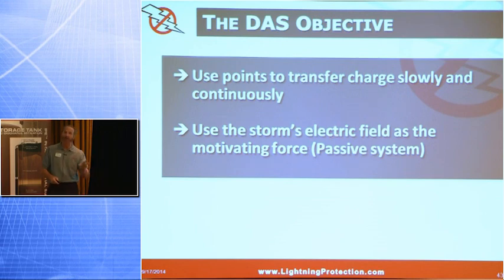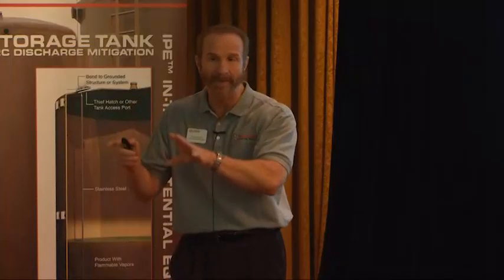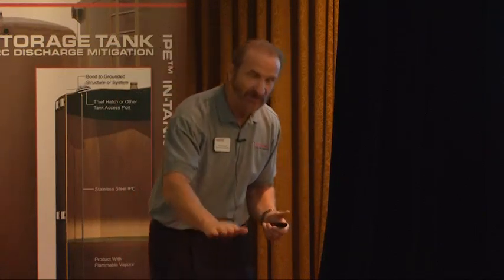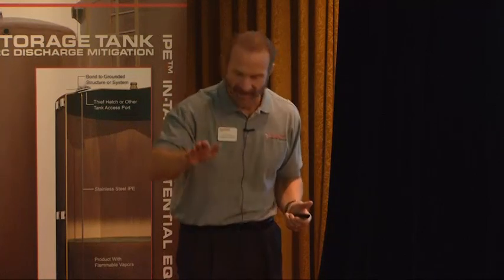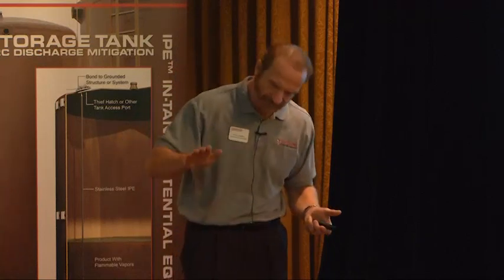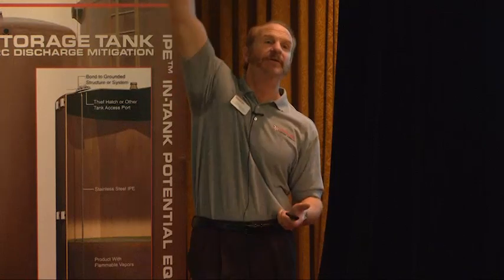And we do know that during a mature electrical storm, there is a very high electrostatic field developed, at least 5,000 volts per meter, up to 30,000 volts per meter. And remember, that's per meter, per air. So obviously, if we start at ground level, let's say 10 kV per meter. Let's say my storm that we're working in right now, that electrical storm has 10,000 volts per meter of charge in the air. So keeping it simple, making it linear, you have 10 kV for the first meter, 20 kV for 2 meters, 3 meters.